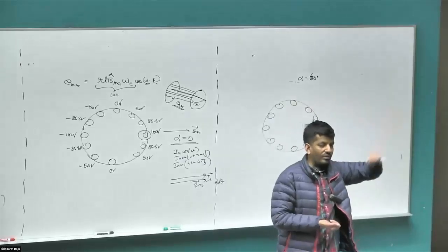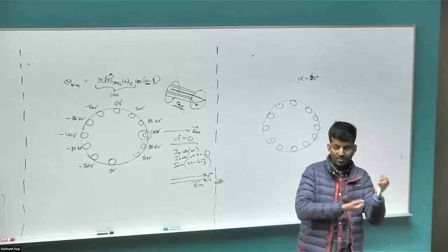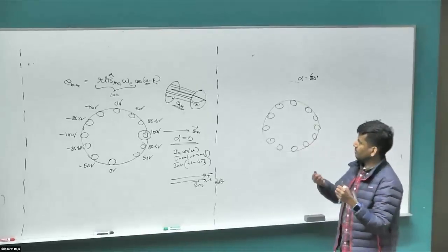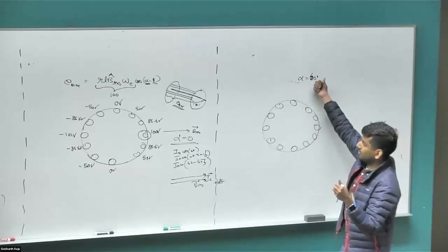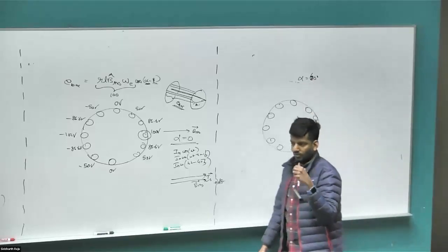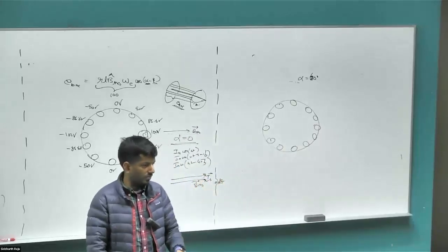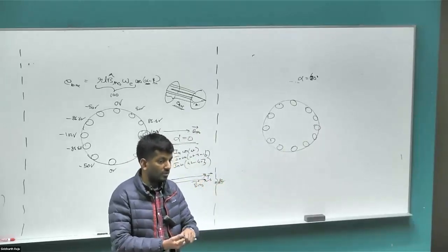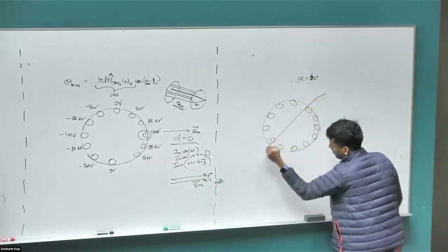Or basically saying omega t has passed to 60 degrees. Right? Some time has passed and the currents have moved or changed around in the phases, and the MMF space vector is maximum. The maximum of MMF is pointing at 60 degrees, or the space vector is pointing at 60 degrees. Which of the bars would have the maximum voltage across it? So the 60 degree one. 60 degrees. So this is our MMF space vector.